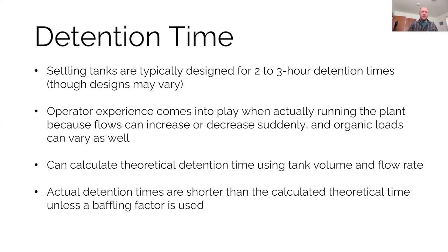If you want to do detention time calculations, go watch that wastewater math video. But a lot of times you need to include a baffling factor. A baffling factor just means: is the water moving through a chamber all equally, or is it short circuiting? Is it going through quicker in one area and slower in another? Of course, these basins are not designed perfectly, or it's not possible to design it perfectly where everything flows through at exactly an equal rate.